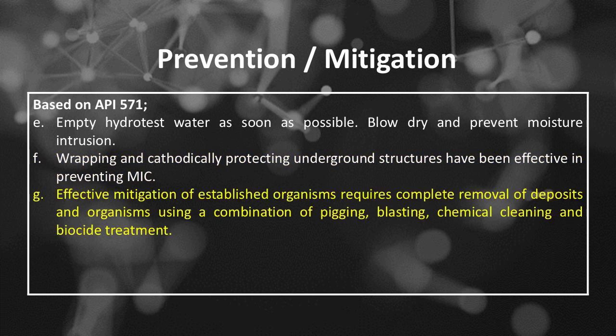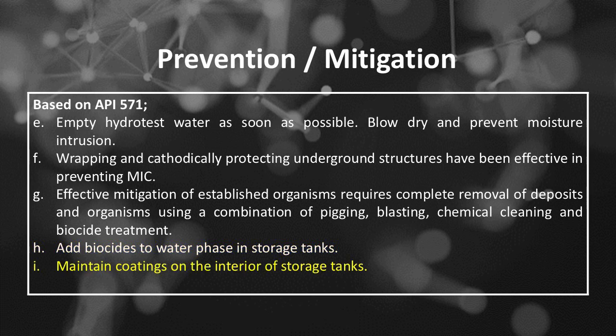Number G, effective mitigation of established organisms requires complete removal of deposits and organisms using a combination of pigging, blasting, chemical cleaning and biocide treatment. Number H, add biocides to water phase in storage tanks. Number I, maintain coatings on the interior of storage tanks.